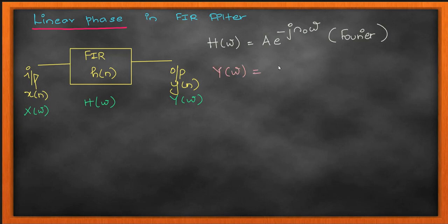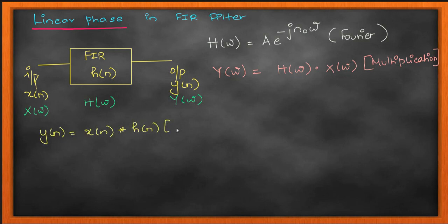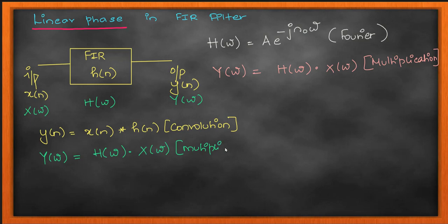So in the case of a linear phase, FIR filters have a linear phase, and this delay is constant throughout. This is very important because you are sending a signal at a certain frequency, your FIR filter is processing it, and you are getting an output. When I talk about constant delay, it means your phase change is also constant. It is only dependent on the frequency, which means the delay is constant throughout all the frequency ranges.